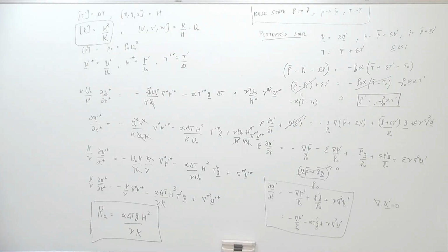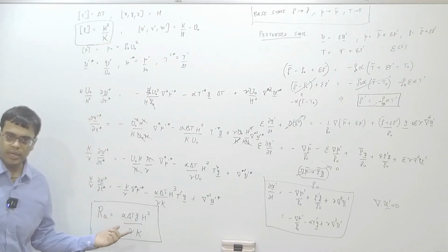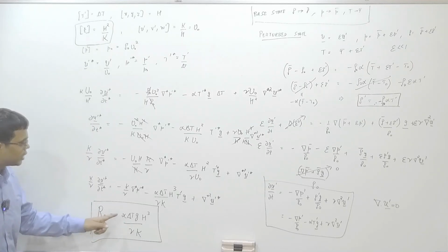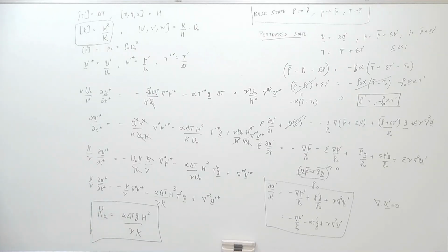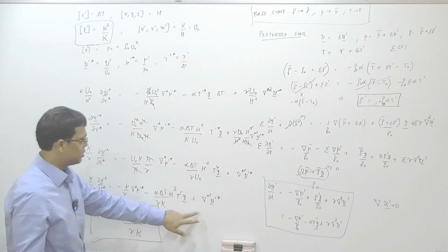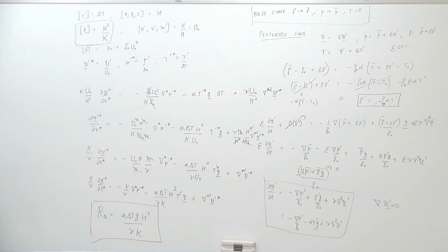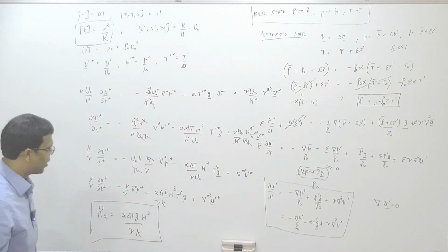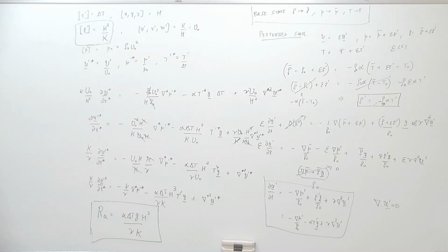Okay, basically you can look at this problem, you can look at the Rayleigh's number as a product of two non-dimensional numbers. I will leave that mathematical manipulation to you guys, that one, you can get it as buoyancy force divided by viscous stresses, let us not call it shear only. So buoyancy force over viscous force, you can write it like that. And then you will also have to write it like buoyancy force over viscous force times the viscous over thermal conduction time scales.